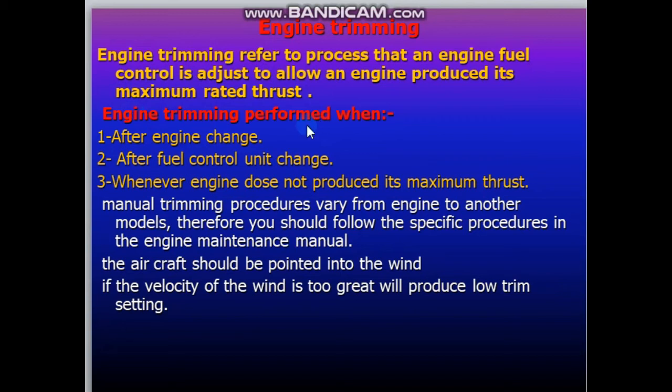Engine trimming is performed if we have one of these things: after engine change, after fuel control unit change, and whenever the engine doesn't produce its maximum thrust. So if one of these three things happens, you have to make adjusting or trimming for the engine.